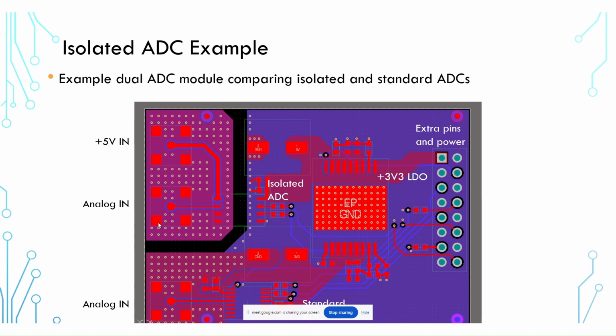Now, this analog input could be a pretty low-level signal. And in fact, if you start looking at the voltage ranges that can be sensed with an isolated ADC, they're not huge voltage ranges. As I recall, the part number that was used in this project had a full range voltage of about 1.25 volts, if I recall correctly. So these are really being used to measure a low-level analog signal in a noisy or unsafe environment where you would need galvanic isolation.